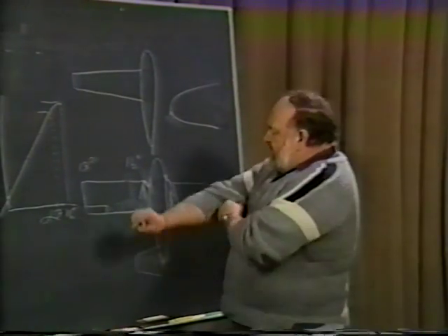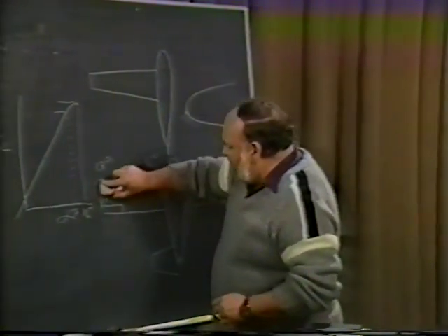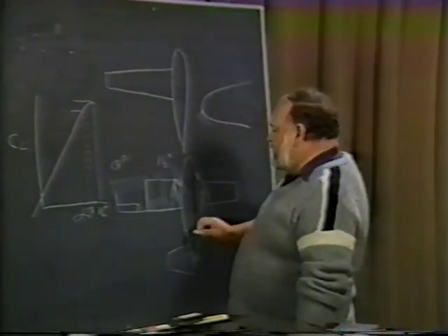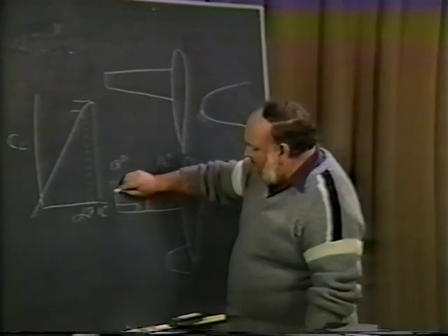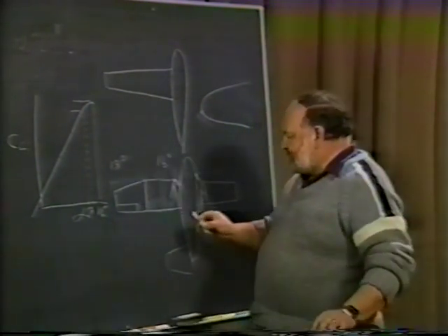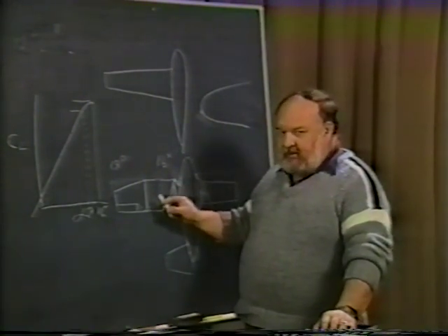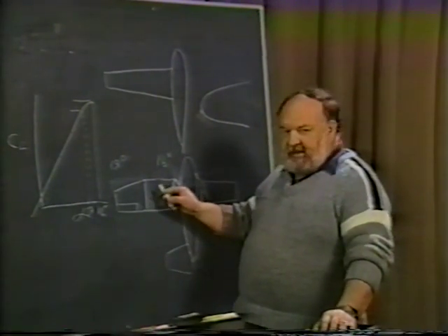You've seen some airplanes maybe too where they'll go to a trapezoidal section, and by that I mean to say that it's constant chord out to the tip, and then they sweep it back on the leading edge. Well, if this is done exactly right, you can develop a good stall pattern, but in many cases it isn't.